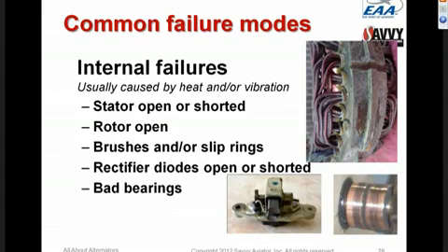There are 2 bearings in every alternator, one on the drive end, one on the non-drive end. Obviously, if the bearings start to fail, there'll be problems. If it's a gear-driven alternator, the hub will probably shear. If it's a belt-driven alternator, it'll start causing the belt to slip and so on.